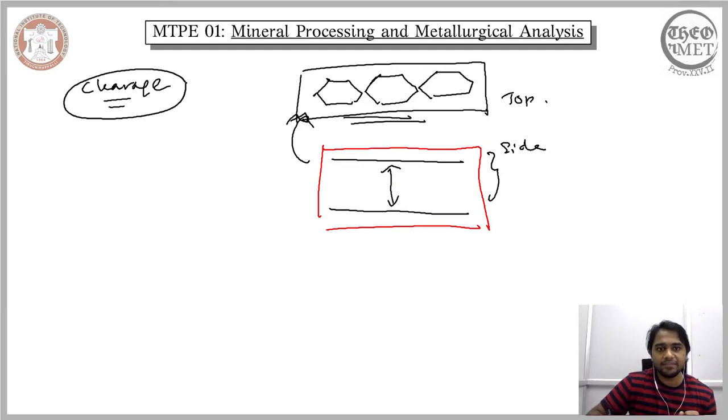In the context of minerals, whenever you try to break or fragment a mineral, almost always the fragmentation occurs along a particular plane, and this is what we refer to as cleavage. You take a pristine single crystal of a mineral, apply a uniform load, and you always observe that the mineral breaks along a particular plane. This is what we refer to as cleavage.